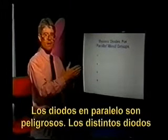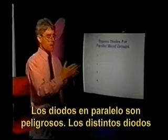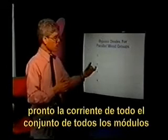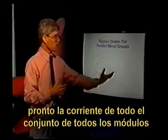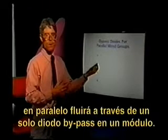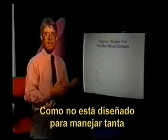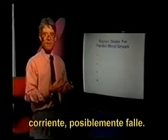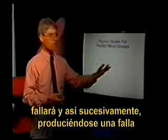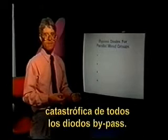Diodes in parallel is a dangerous thing. Different diodes will start conducting more current before other diodes. And all of a sudden you'll have the full array current from all of the parallel modules flowing through one single bypass diode in one module. It's not designed to handle that much current. It'll probably fail. Then the next diode that's carrying current will fail, and so on. And you'll get a catastrophic failure of all the bypass diodes.